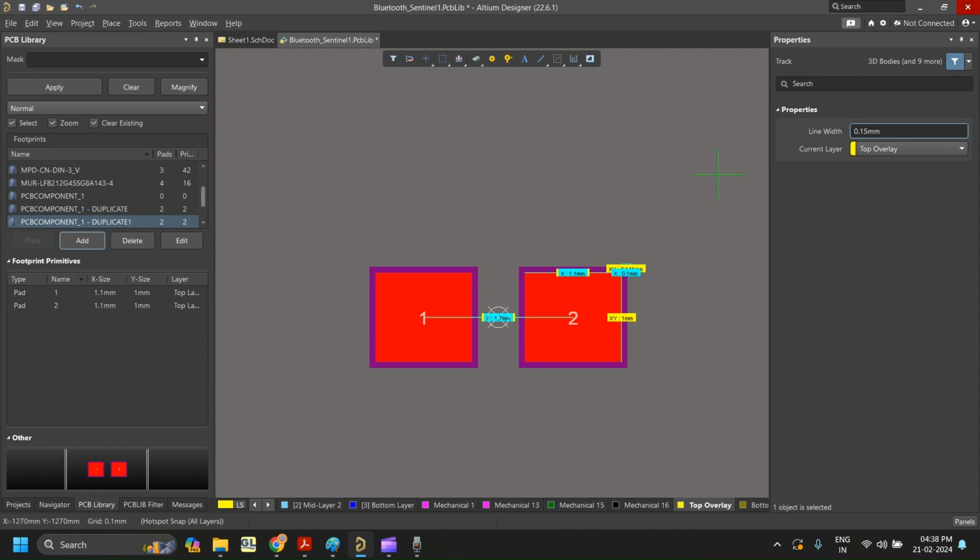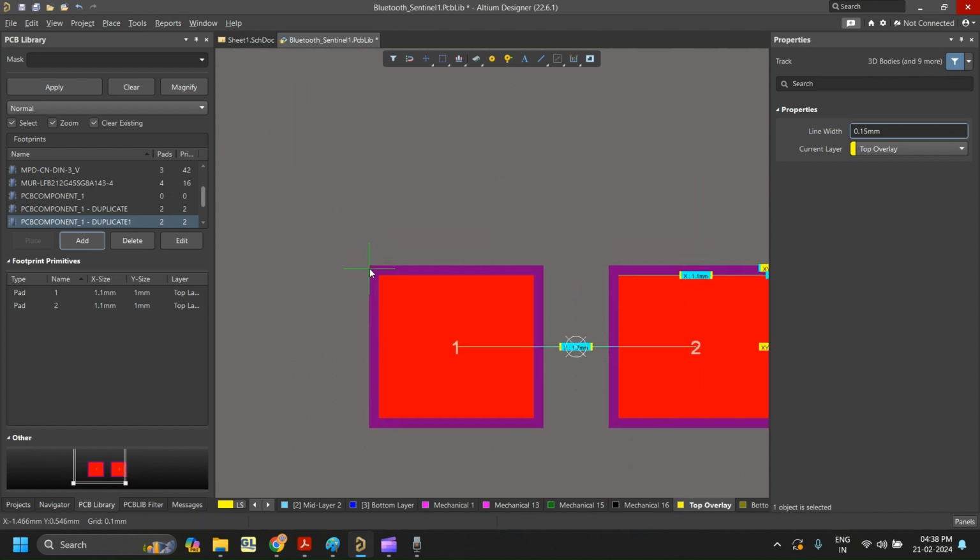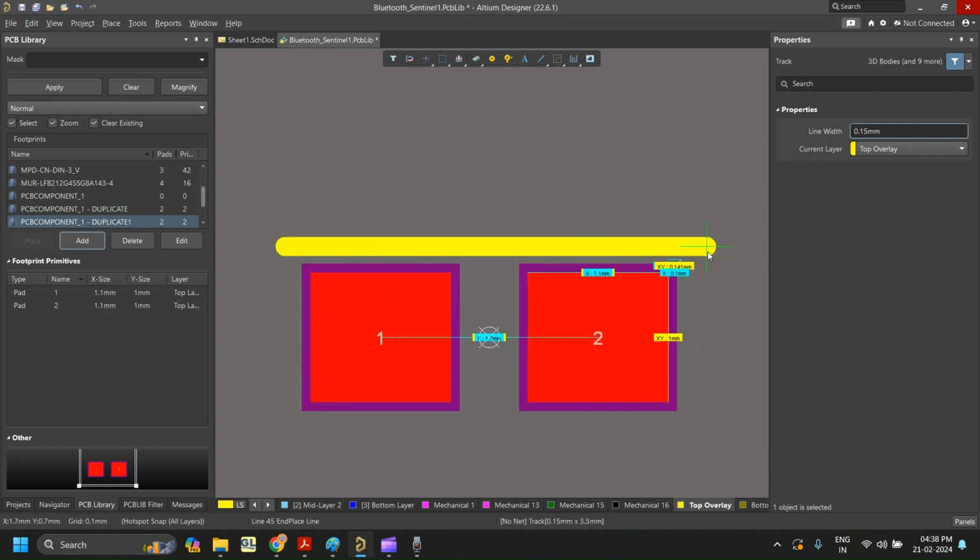Okay, the maximum will depend upon the aspect ratio of the component. And there are some rules, like silkscreen should have 0.2 mm clearance from this. Okay, that is also there. So I am defining the silkscreen like this, and silkscreen can be in any form.